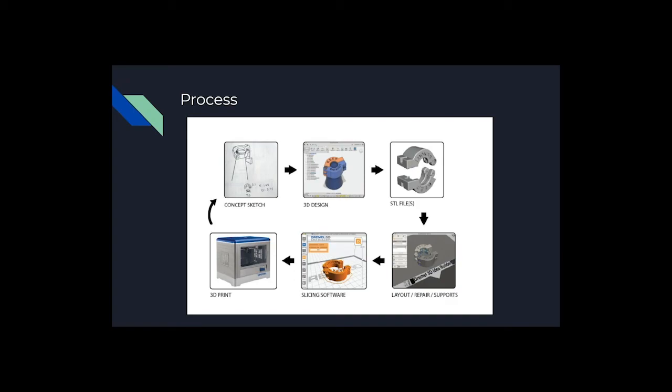So, you've exported your files, you're almost there to print. So now you have to prep your printer, and that can vary from printer to printer, but most of the time you just have to make sure that the filament is loaded, the print bed is clean, and it's preheated.